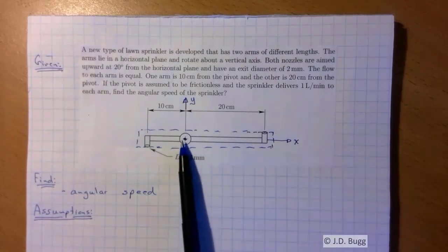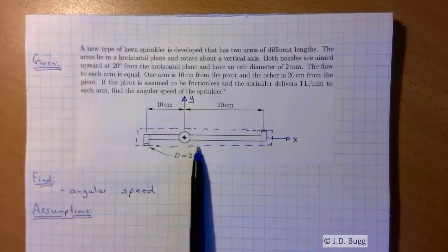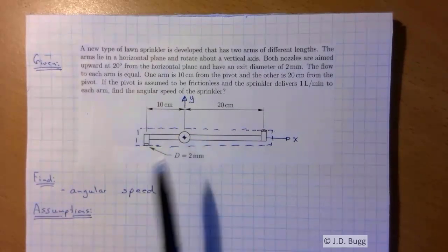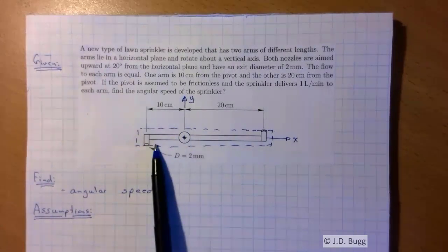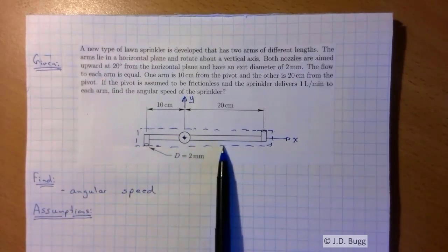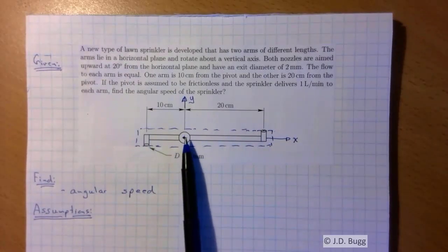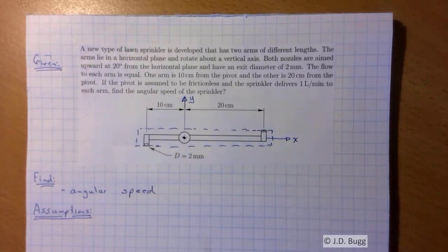Well, the inlet is at the pivot here, right? There's a garden hose probably coming from somewhere, and it enters into the base, and then it turns a 90-degree corner, and the water comes up through this pivot and splits into each of these arms. So there is an inlet to this control volume. Just because the sketch is so simplified, we can't explicitly see that inlet right away like we can the exit. But we need to keep in mind there is an inlet, and it's right at the center here at this pivot. So we'll be discussing that further as we discuss our conservation of angular momentum equation.